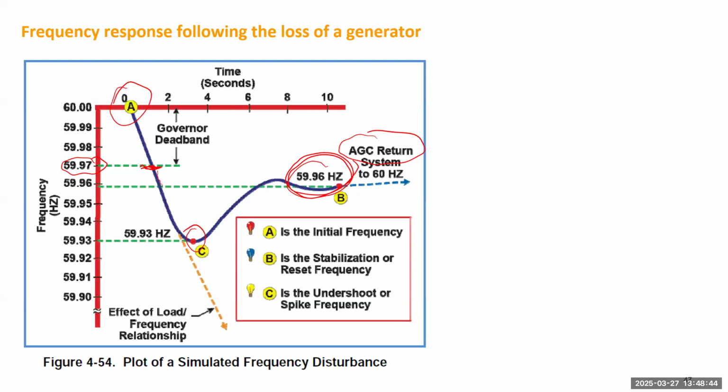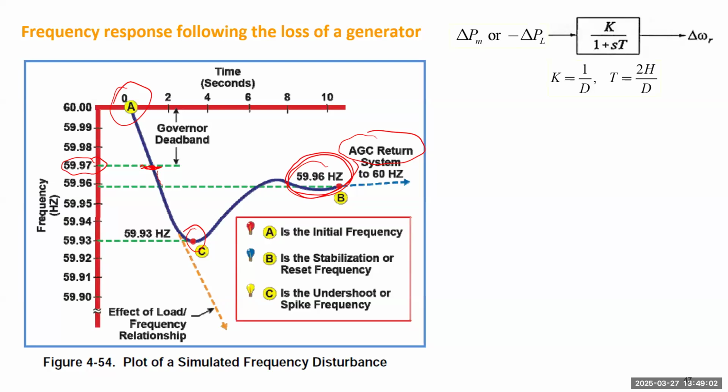The power electronic interface makes all the control responses very fast. Very fast response may be good in normal conditions, but if there's any disturbance, they can also respond very quickly in the bad way, which means they can decrease or increase the slope to make the frequency decline faster. So we go back to this example with a single component. If we model the total generation of the system through a total inertia constant H and the total D, the frequency dependent load here,